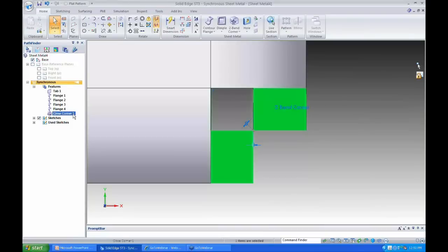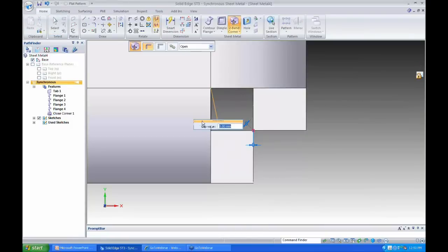At this point, I'm going to change back from closed corner to overlap, and then talk about what this overlapping corner is. Remember, our gap value is 0. If I change to overlapping corner, it will give me two options. The first option is overlap ratio, the other one is gap. The meaning of gap is the same, it takes the same value we used. If I say 0.5, it's going to do the same thing, but this overlap is something different.